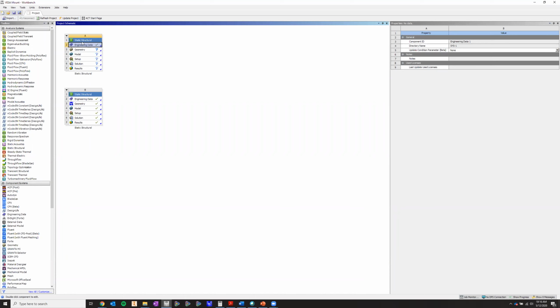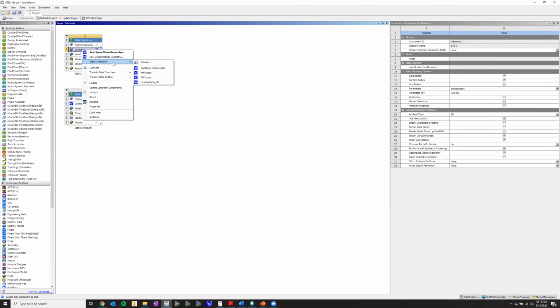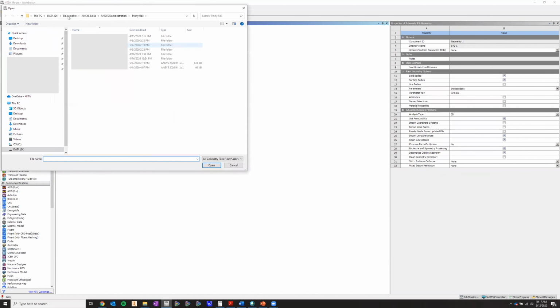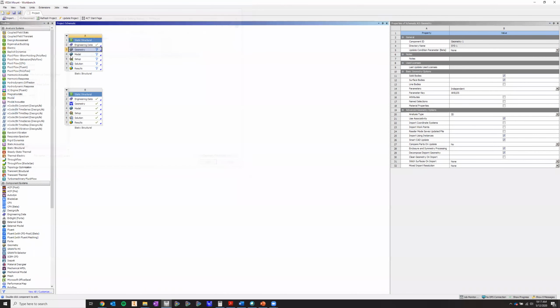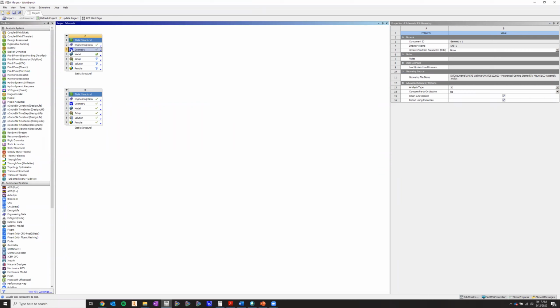Now I move on to the next part of my top-down workflow, which is A3, geometry. Where did I complete my design? In another CAD software, or possibly in Ansys itself, which has its own geometry manipulating tools. But I could right click, import, and browse here in the geometry area, search for our VESA mount, and it's already imported. So now A3 is complete.